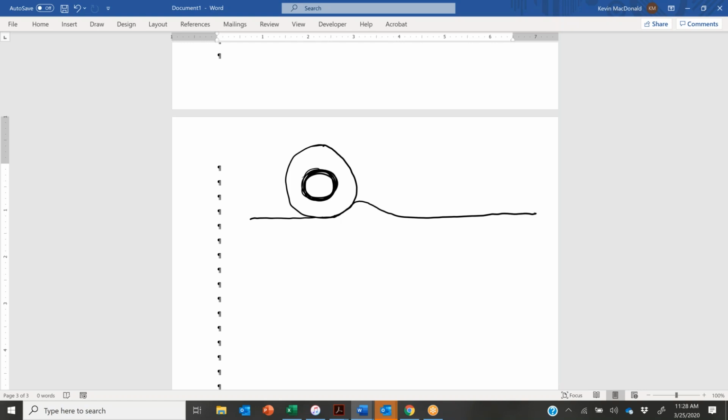There is some soil that sits at some angle, don't know what it is, as the vehicle is typically pushing into the soil. And this has the effect of the vehicle always going uphill, because it's climbing out of a hole that it's creating itself.